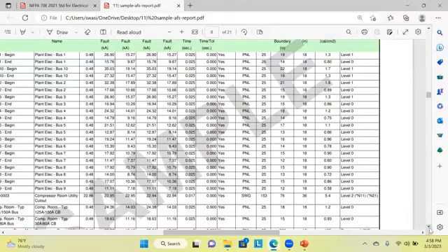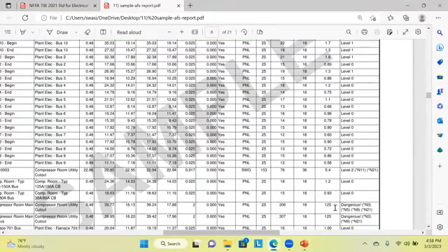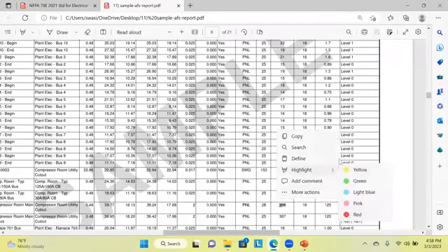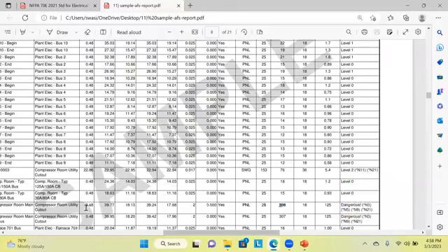Or for this incident energy, for example, 125 cals per centimeter squared, it is 306 inches. Just convert 306 inches into feet and inches. You will find that for this 480 volts, the arc flash boundary will be the outermost, then the limited approach boundary and the restricted approach boundary.